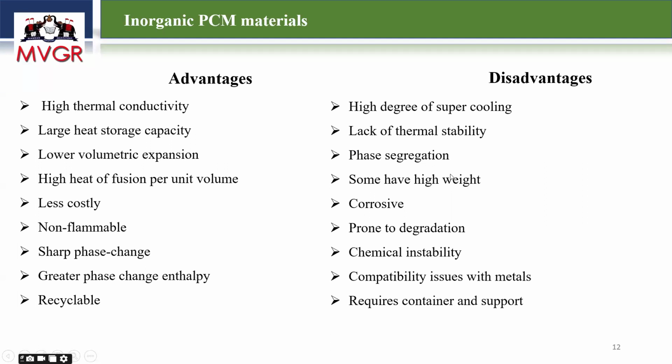It is a little bit heavier as compared to organic phase change material, and it also has corrosive nature, and phase segregation will happen. So phase segregation means whenever it is releasing the heat, it has to come back to the solid state. But sometimes it does not fully complete into the solid state.